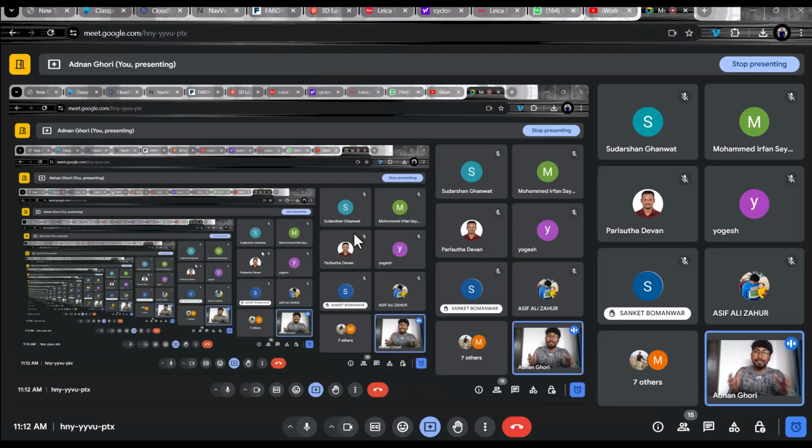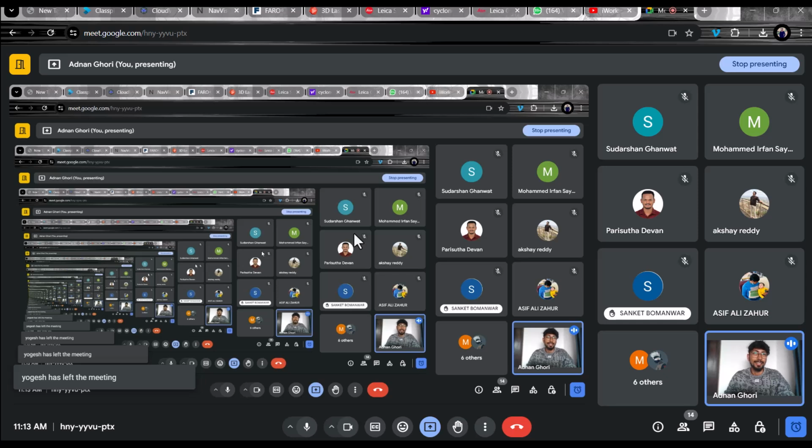Let's say there is a door, and the door is pretty difficult for you to model in this particular project example, and you don't have a family for it. So what you will do is make this particular door as a family in your project. It will take you maybe 4 hours, 5 hours, right? To make a simple door family, maybe it will take you 1 hour if you are experienced enough. But if it's a parametric door with certain parameters and a particular architectural design, it may be more difficult for you.